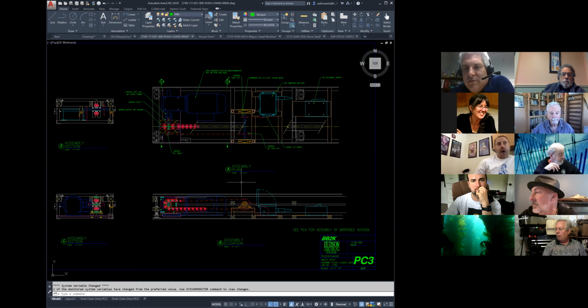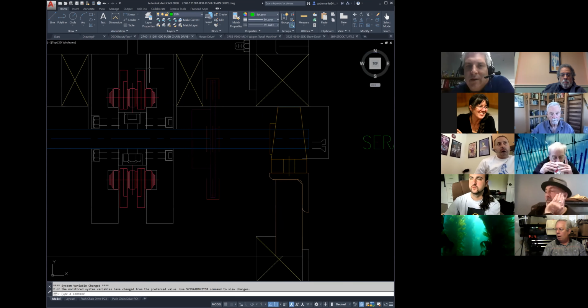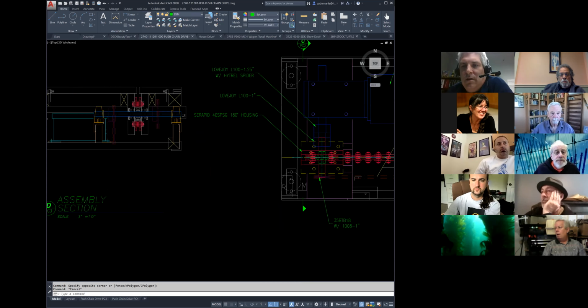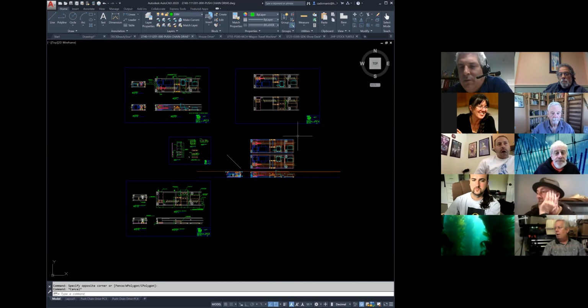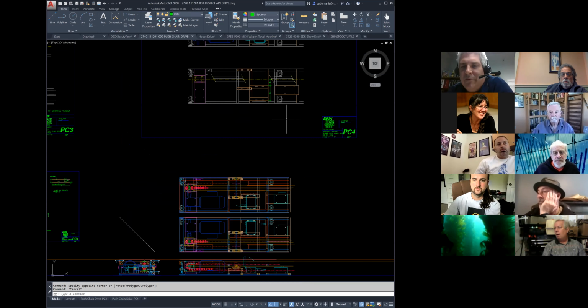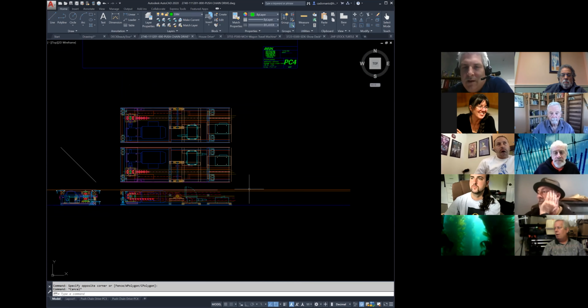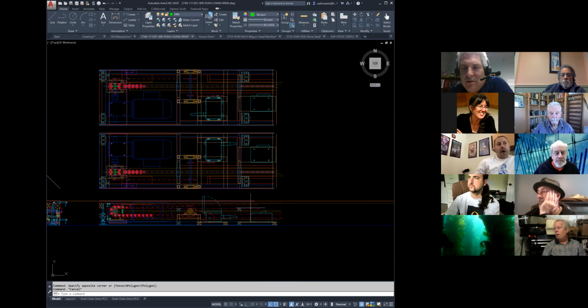We made our full stage guides out of just some plastic UHMW blocks here. You can see that was fairly easy router or even table saw work that guided the chain across the deck. And it worked pretty well. We did this at the request of a customer for a touring application. So we had half stage 32-foot tracks that we had to drive, that in a 16-foot platform, we could store all the chain for that track. And that was how it toured.